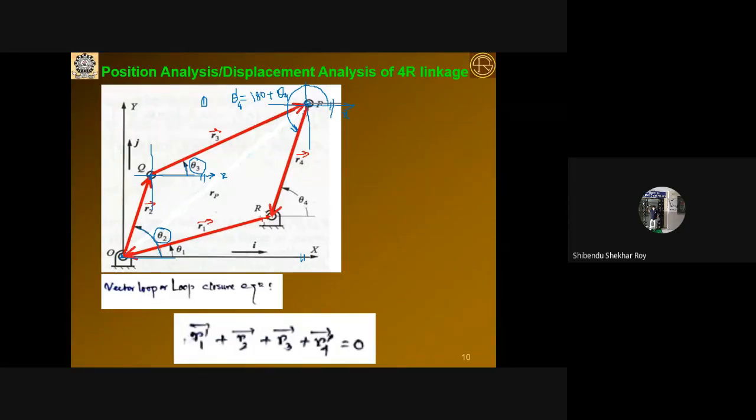Now your angle here, it will be the theta 4 prime, because here you should not write it this way, it should be like this way. It shows both directions you put the angle. That means the angle of this line with respect to the parallel to x-axis is theta 4 here, but this is not the theta p. Theta p is what I mentioned in a generalized way, no? That is, vector rp equals rp cos theta p. Theta p is this one.